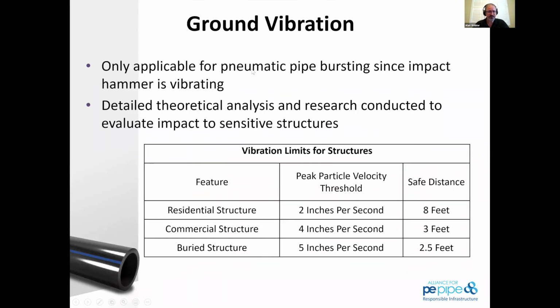So ground vibration is really analyzed for pneumatic pipe bursting. As we're moving that impact hammer across, it's sending a wave out into the soil condition. A scientist, Dr. Alan Atala with Bowling Green University, had studied the vibration limits. It's sending the peak particle velocity through the soil. And when we get into residential or sensitive structures, we're really looking at staying away from them some 8 feet. Buried structures, retaining walls, or other things that are fairly solid, we can be a little closer.